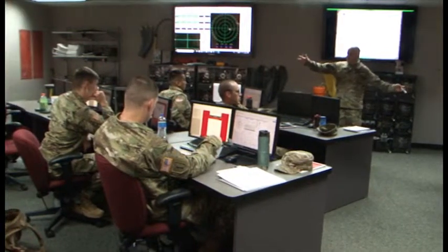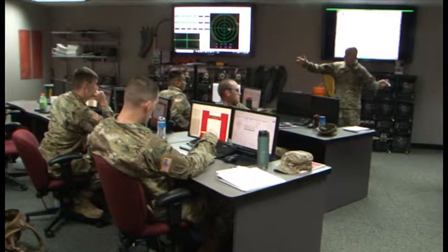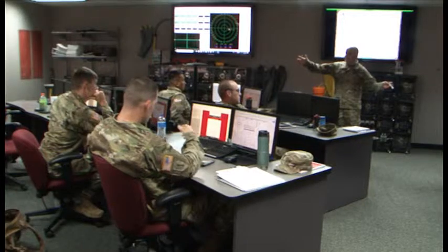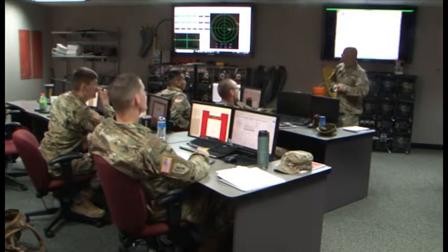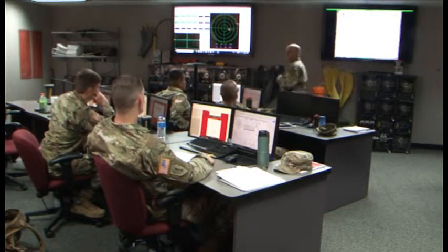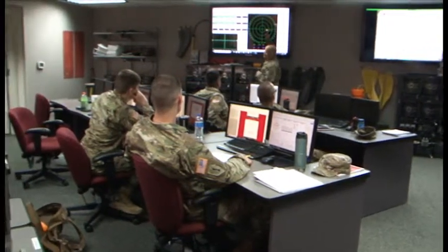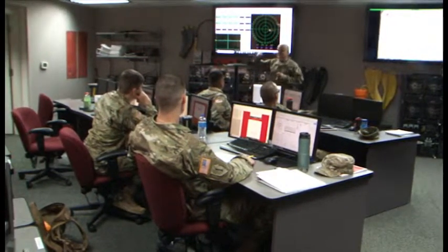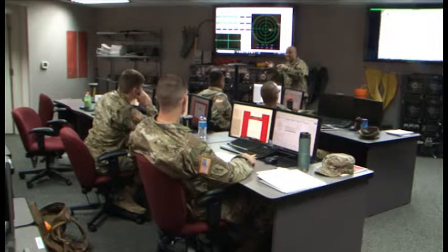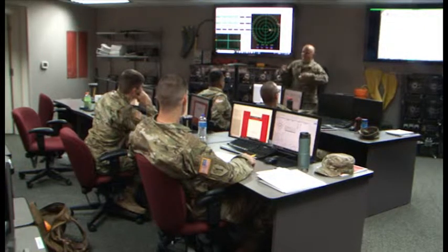There's two kids pulling at this point, and it's pulling in that lagging direction. The current lagging the voltage, right? Voltage leading the current in that capacitive circuit. So that phase angle that we're talking about, or a phase angle, depending on what we're referencing, is the angle from that zero mark of whatever that resultant vector is that we're looking at.